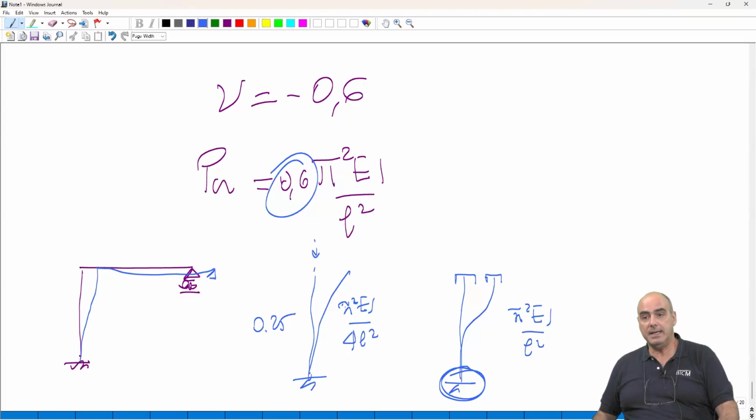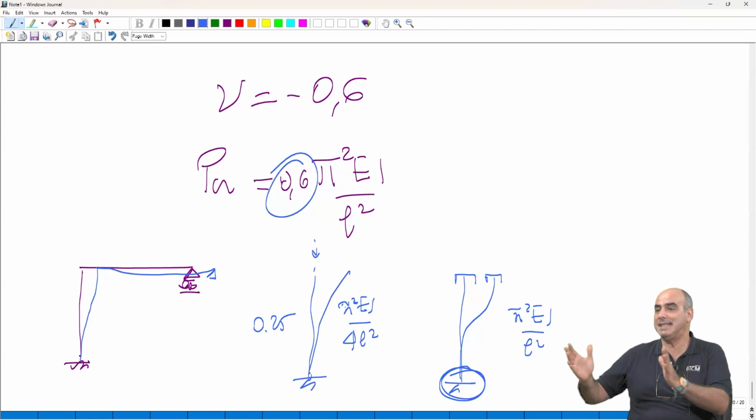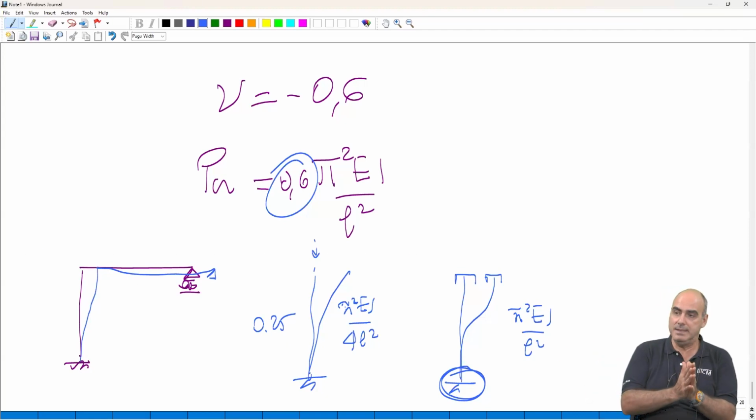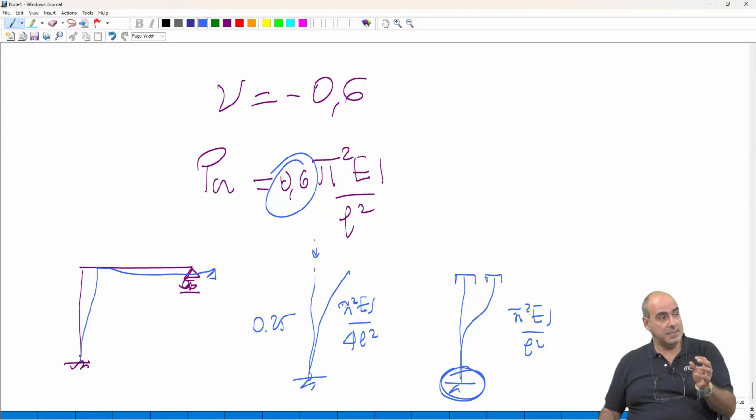And the other thing is that nowadays we speak about the demountability and reusability of precast elements. So you must guarantee, if they have to be demounted and reused, that they stay sound, that all that happens is in the joining elements. So for this reason, the connection elements are of the utmost importance. And we will see them tomorrow.